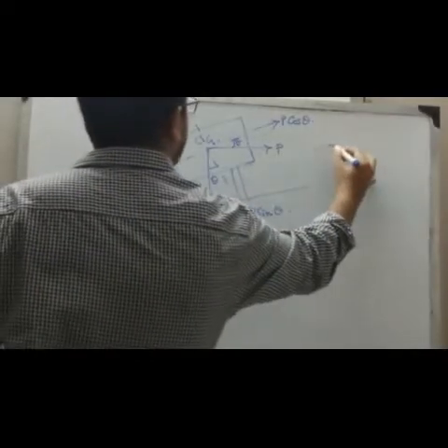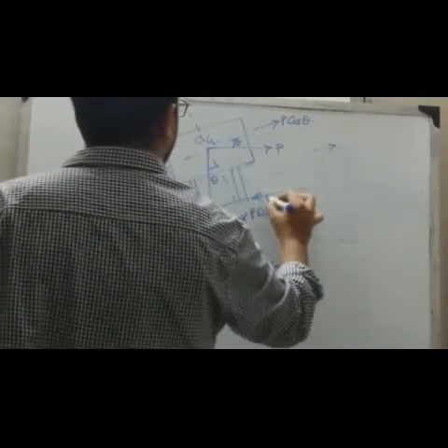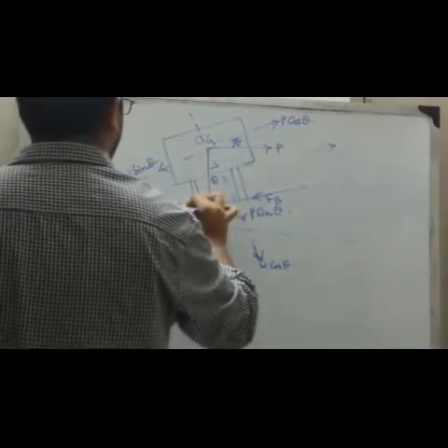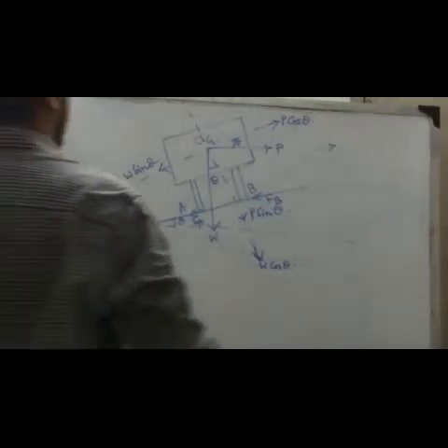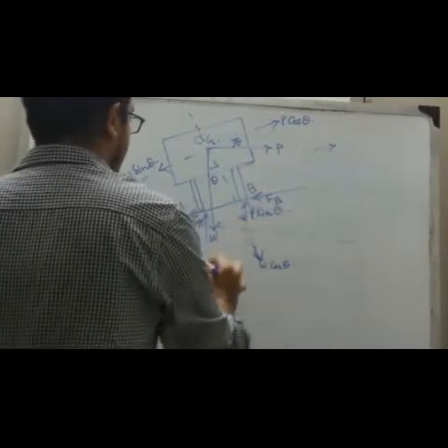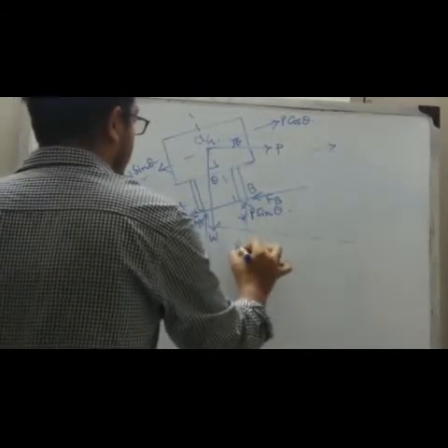Now there are also two forces, that is frictional forces. The vehicle is moving in this direction, so these frictional forces are FB and FA, if these points are A and B. And as the total load moves in this vertical direction, there are two reaction forces, RA and RB.